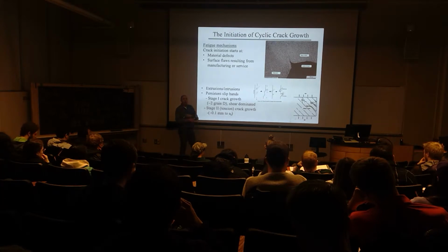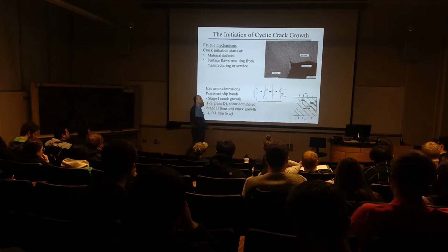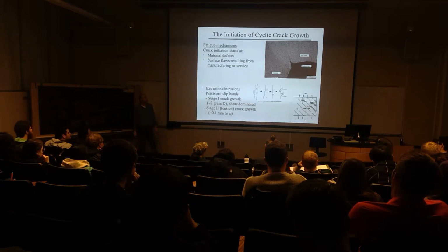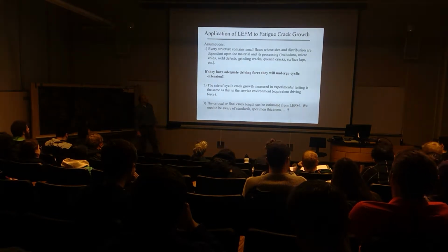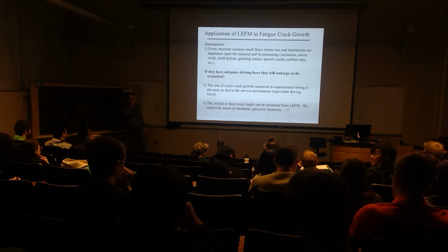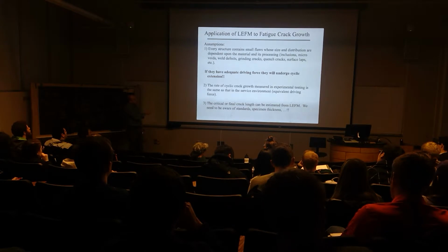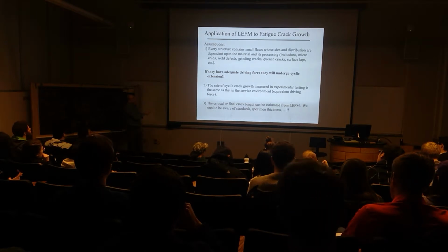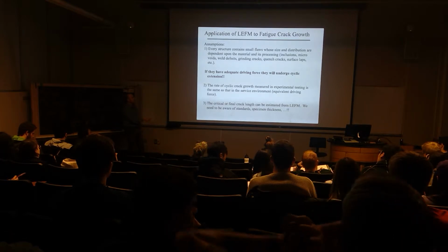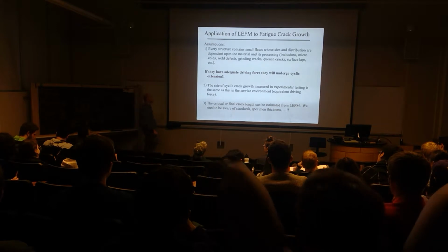If they're localized, what can happen is they can develop small cracks that then transition into a very well-defined crack that grows under mode 1 loading or tension. So many sources. So what we want to do is we want to say, hey, we might have flaws in structures, and then what we want to do with that is we want to say that we know that they can grow if they're subjected to an adequate driving force or an adequate magnitude of stress under their service loading condition.